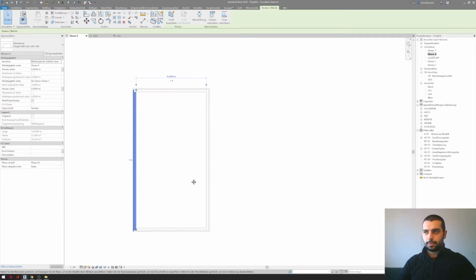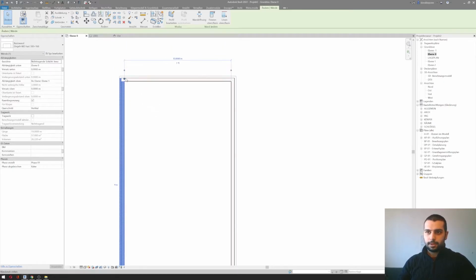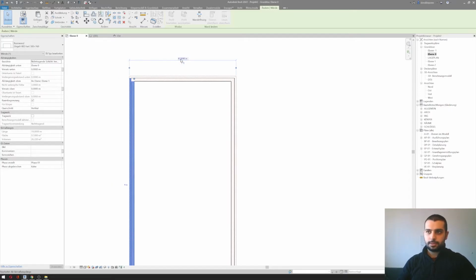Like this. So let's say I want to keep them at 10 meters, but from the exterior, not from the interior. So as you see in my temporary dimensions, there are two nodes. These are small dots that I can click and drag. So I'm holding my mouse button right now. And I bring it to the exterior side of my wall. I click on this one, drag it on the exterior side of this one, and I make it 10 meters.